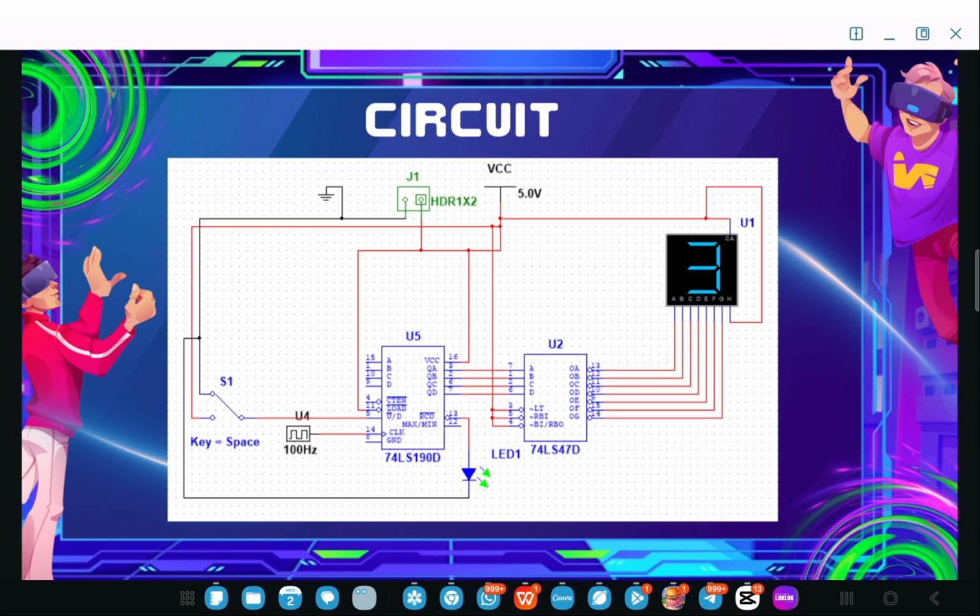We have 3 logic gates: AND gate, OR gate, and NOT gate, the inverter. The AND gate is used to combine signal Q output and control signal C. The OR gate is used when we need to allow either of 2 inputs to activate a function. The NOT gate is an inverter. The inverter is used to reverse logic. When C is 0, we use NOT C to get 1.